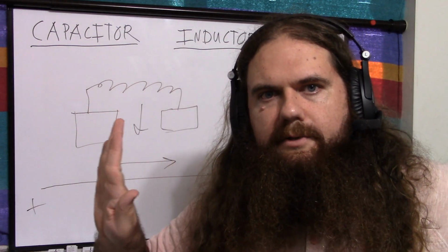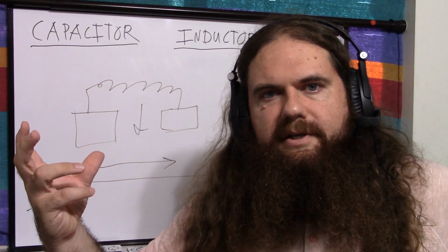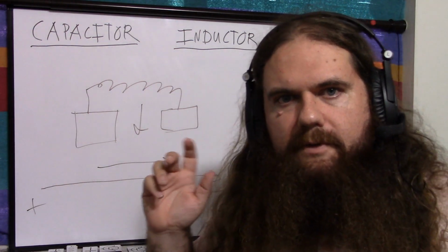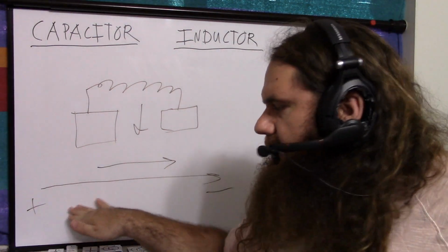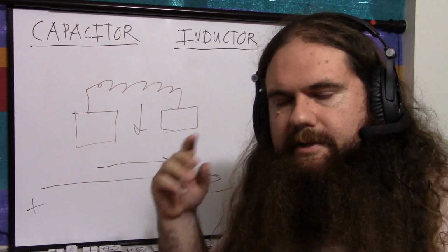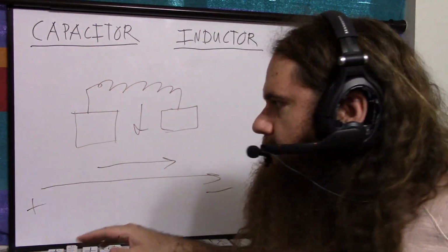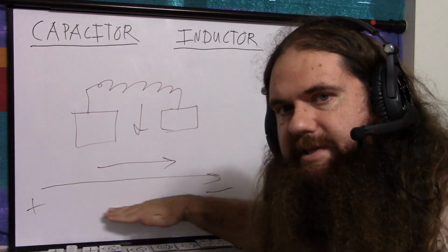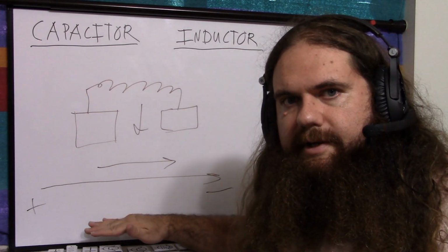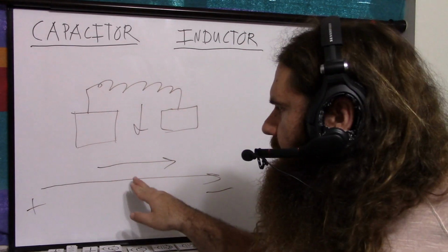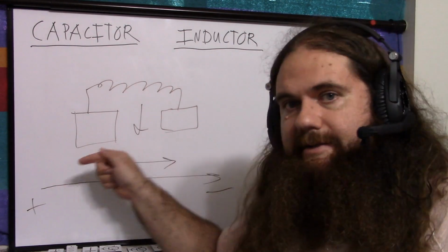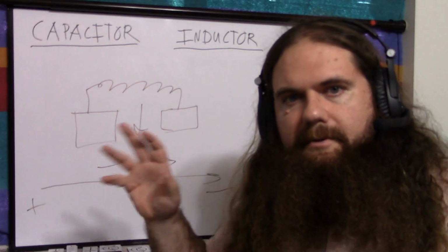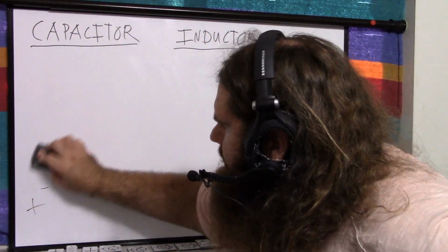Inertia resists you trying to add energy to the system, and the process of trying to remove energy from the system is to basically just work against it instead of it working against you. Now, unlike the wrecking ball, you don't have to apply a backwards current to stop the inductor. It's not physical inertia. It's just an analogy. Basically, it'll just charge or discharge, strengthen or collapse to whatever the standby current is, the stable, stationary current is. So that's how an inductor works, and that's why it's said to oppose a change in current, because it literally does with its inertia. It provides current when it's discharging, and it takes the power away when it's charging. So that's the fundamental mechanism.